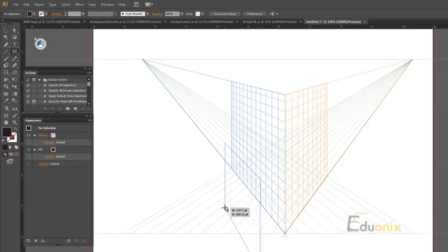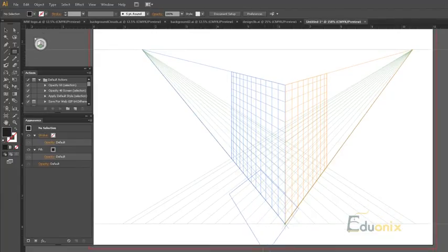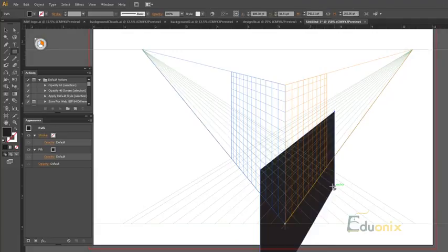So I did a rectangle shape, and there's a much easier way, and that's just to press 1, which is the blue, the left side, 2, which as you can see is lining up parallel to the bottom, and then 3, and this is parallel with the right shape. So by pressing these numbers, you can achieve your perspective before you let go of the mouse.